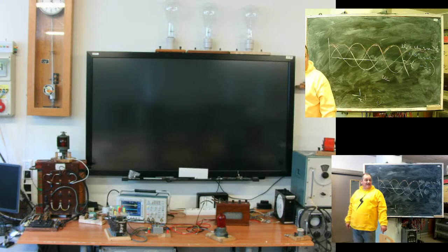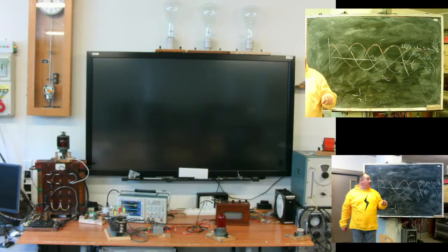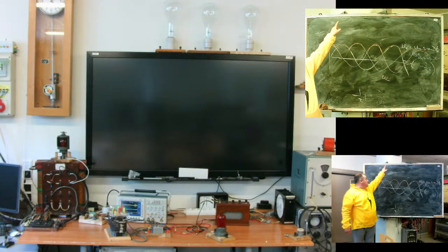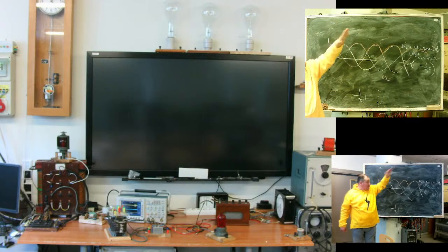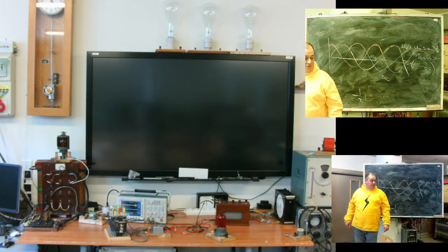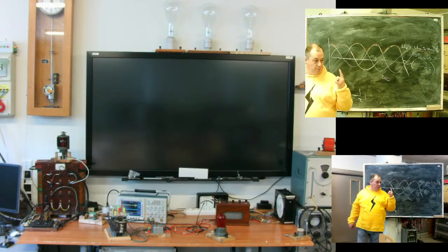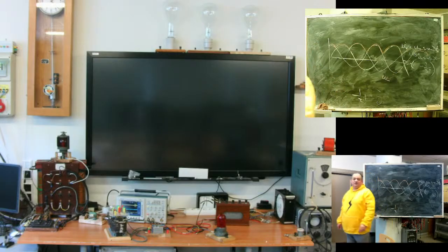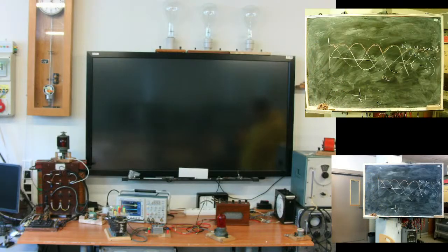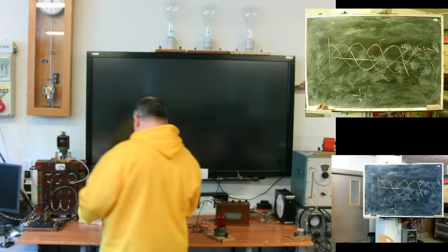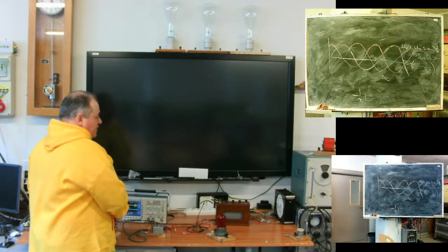For negative sequence, if you have opposite rotation, the shift will be 30 degrees this way. So if you have transformer of 11 group for 50 Hz, it's the first group for 250 Hz, because of opposite phase sequence in fifth harmonic.